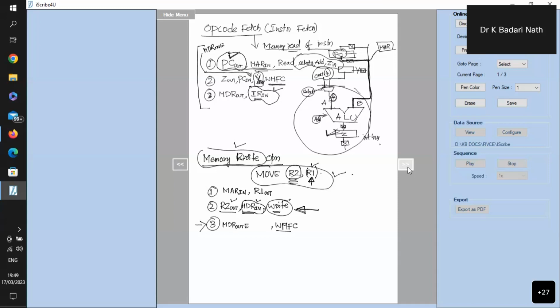So that means MDR in, I've written the data here. In the next clock cycle, MDR out, I can give it so that the data will be returned onto the data bus. So why can I not do both together? Because the same register is involved, one after the other. In the second clock cycle, I return into that. I cannot do the same thing in the out enable, because unless I write the data, I cannot place it. We could avoid this if we permanently connected it, but we cannot permanently connect it. So I've just given this in the next clock cycle.